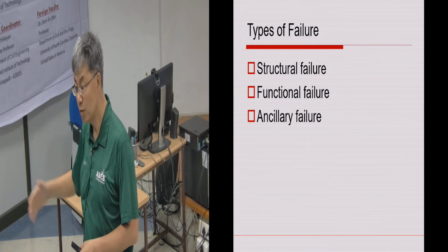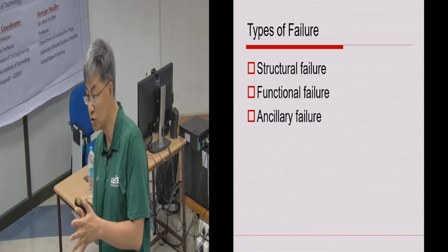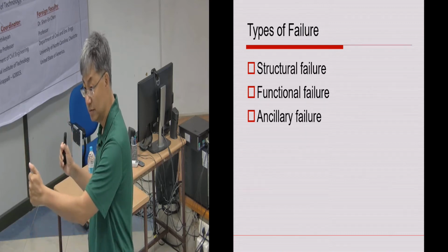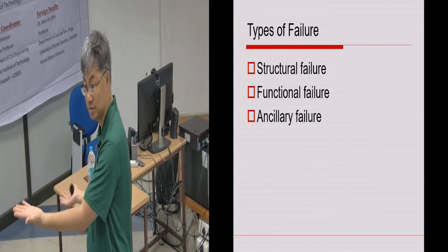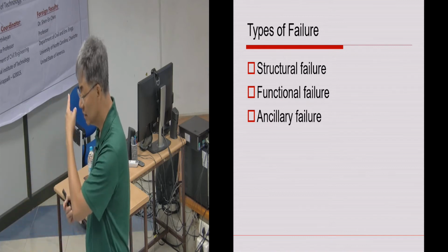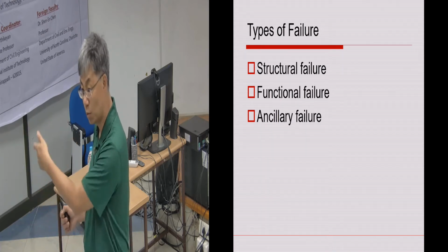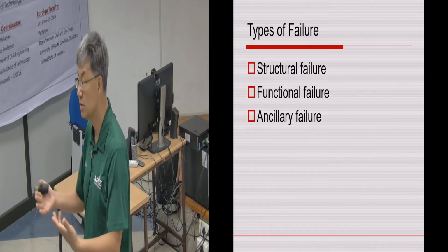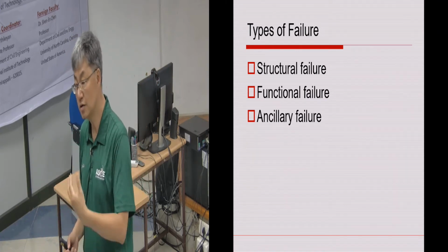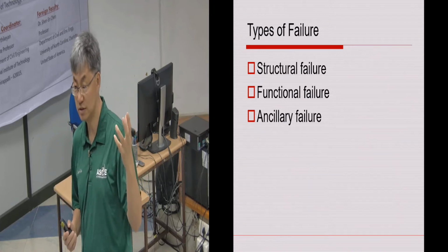Whether it was a punching shear because the soil behind was pushing against the wall, or whether there is a shear failure because of differential settlements on different sides of the building foundation. And so based on the crack pattern of your basement wall, you can define what is the actual problem behind. Same thing with bridge decks, same thing with any wall or beam failure. So those are the things that we can train our eyes to identify, and then define what the damage modes are.